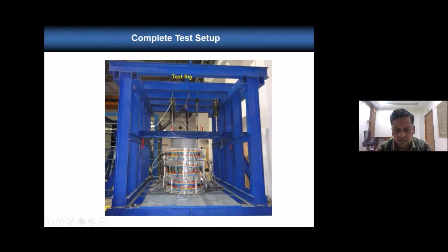Then inside it is the airframe section. This is the dummy section. We cannot apply structural loads directly on the airframe section because they are designed for a factor of safety of 1.1 order. So if I apply structural loads directly on the airframe section, it may buckle locally. So to avoid that and get uniform distribution of stress, we have to design a sturdy structure, and we will fix to that and apply the loads there. So this is a sturdy structure of almost factor of safety of 5. Here there may be higher stresses at the local zone, but as you go away from this, when I reach the airframe section surface, it will be uniform.